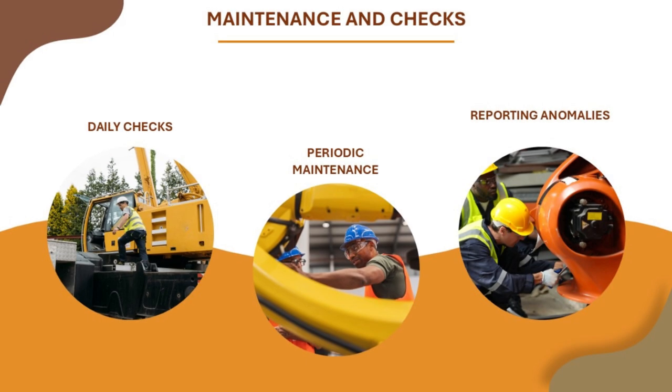Maintenance and checks. Daily checks. Before each use, check the condition of the cables, pulleys, and lifting accessories, the presence of any oil leaks or structural damage, the correct functioning of the safety devices, such as limit switches and emergency systems.